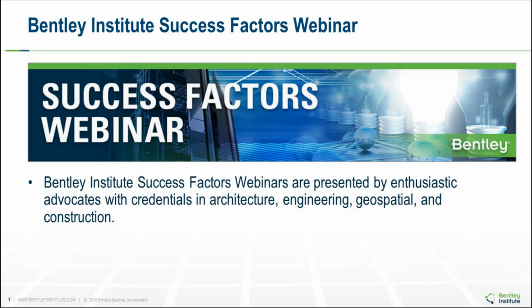Another one there. Do you have to assign support locators to points one by one, or is there another way of doing that? As long as you have multiple points that you want to apply the same support locator group to, they can be assigned at the same time. So you can use your Control or your Shift or your select options and select multiple points and assign the same locator group. In larger models, you probably will have a couple of locator groups, so you just have to make sure you're careful in selecting the right points to assign the right locator groups.